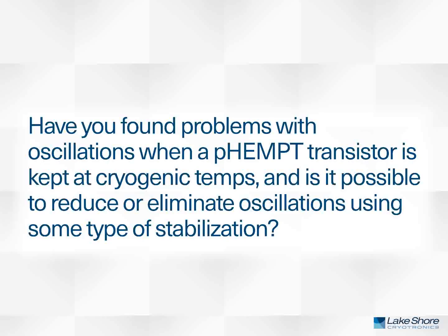Actually, in the pHEMT results that we showed today, when we first started testing those, we did get oscillations. It's a transistor, and as you're changing the semiconductor material, those oscillations can actually get a little bit worse because of the changing resistivity of the channel.